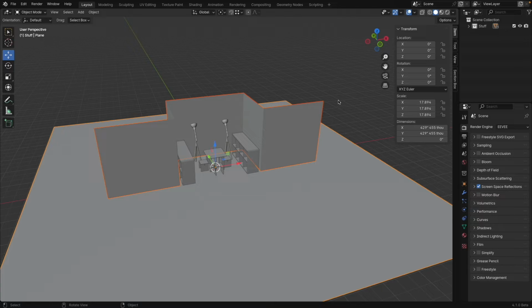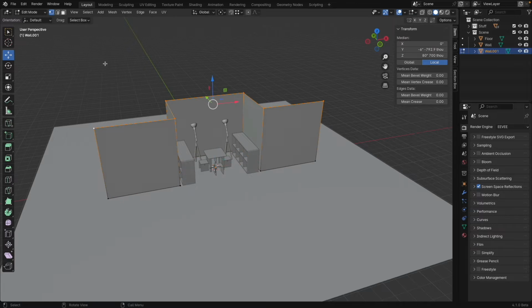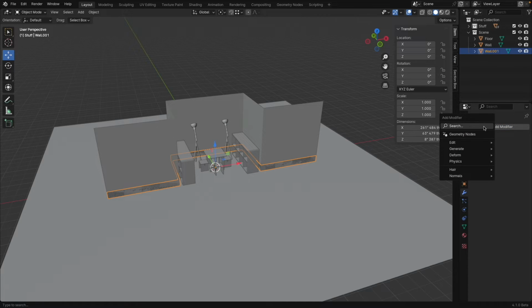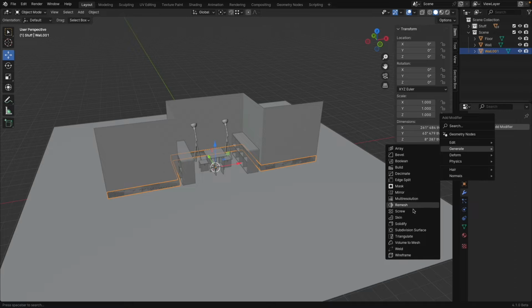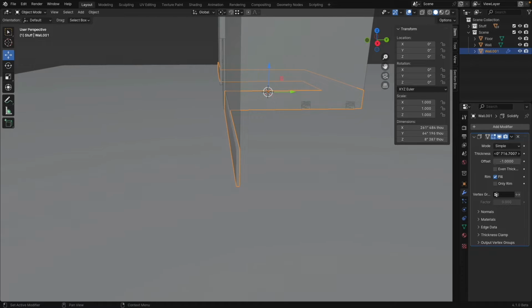I'm going to close this one. Select the wall, select the ground, press M, say new collection, and say scene. And okay, so now I have those in here. This is, for example, the floor. This is the wall. The wall, I make a copy, Shift D and escape. Then I go into edit mode, move these points down. There we are. Exit edit mode, and then I will simply add a solidify modifier. Need to be careful about the direction. Let's say like here. Looks pretty good.